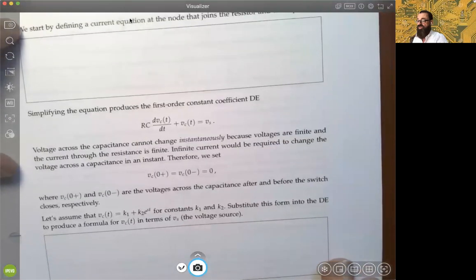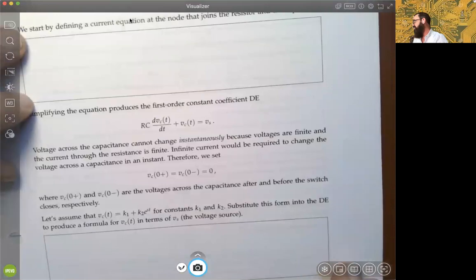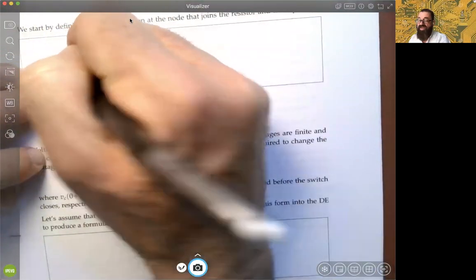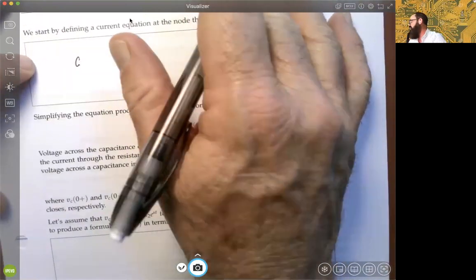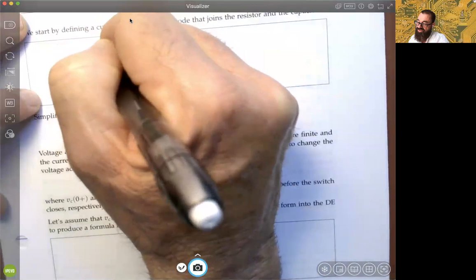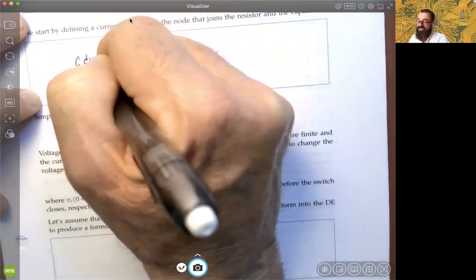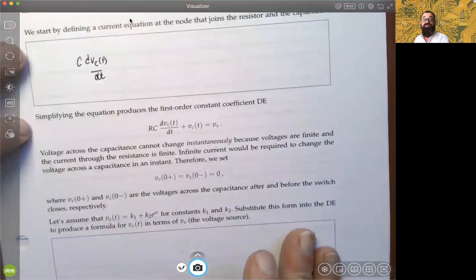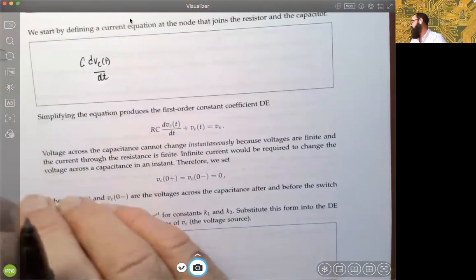Again, using what we know about the representations of current, for that capacitance we would have the capacitance constant, C, times the rate of change of the voltage across that capacitance, dv/dt, all right? And the way we've written it there, we would have it in the passive reference configuration because we're going to absorb the energy, and so we won't put a minus sign there.